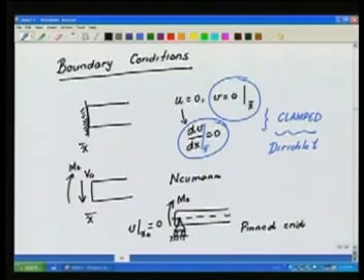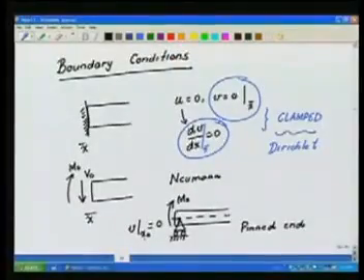You see that, remember what we had said is the displacement and the shear force occur together in pairs, and the bending moment and the slope occur in pairs. So if the displacement is specified, certainly I can't specify the shear force, but here I have done nothing about the slope, so I can apply a bending moment there. I have to apply a bending moment there because slope could be anything. Okay. In general, see, in most of the examples that you see, this bending moment is set to be 0. Okay.